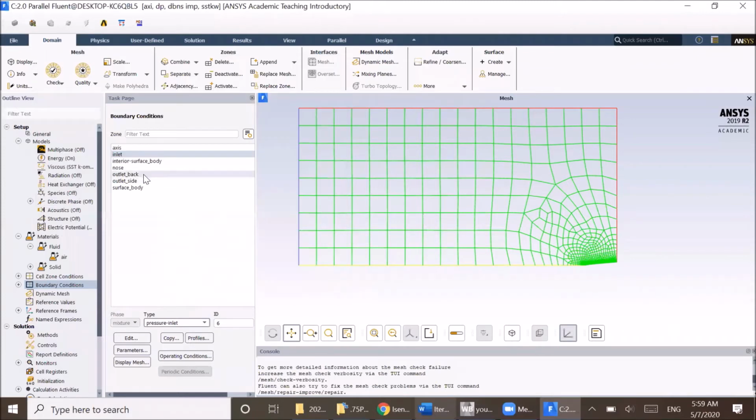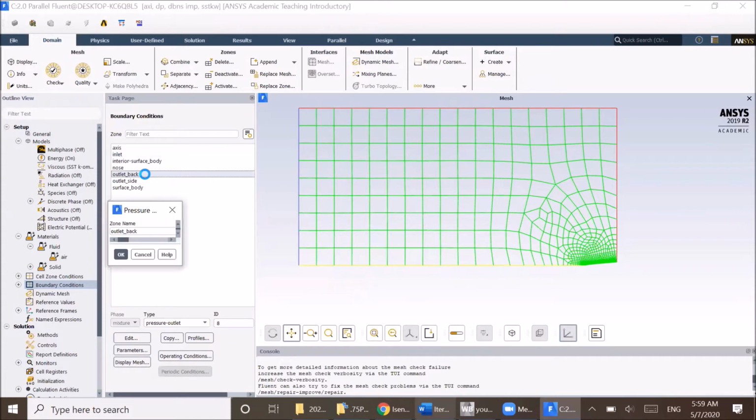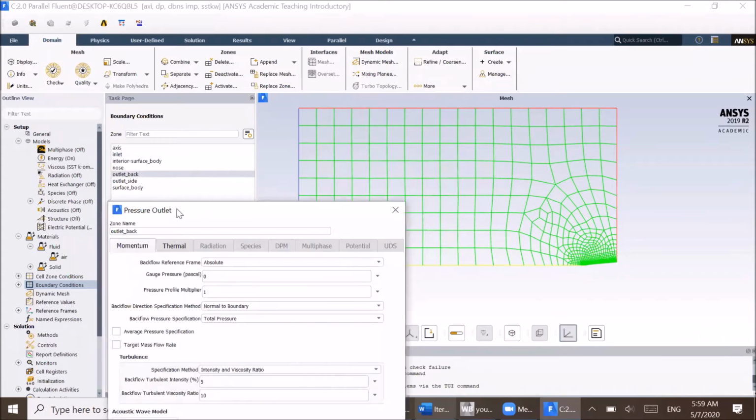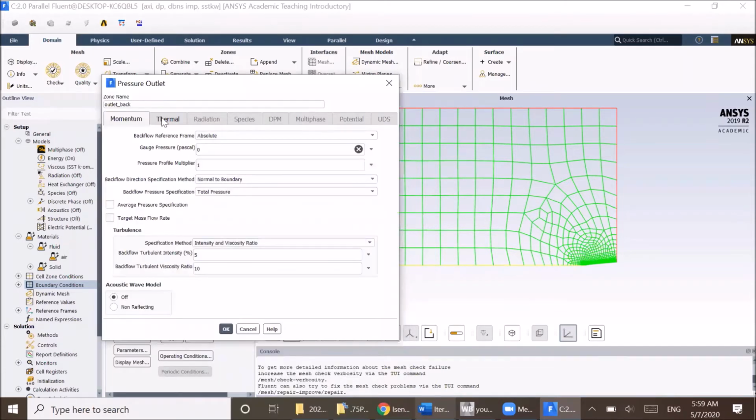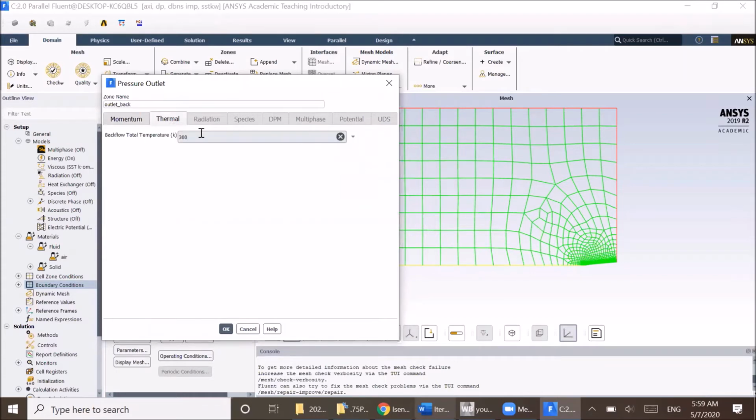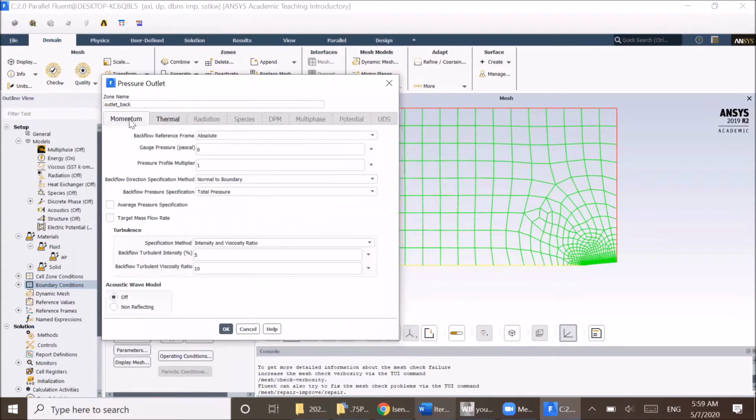All right. Now we also have to change our pressure outlet options. So our temperature is going to be the same one we calculated for the pressure inlet option. And the backflow direction, you want to make sure you have that selected to from the neighboring cell.